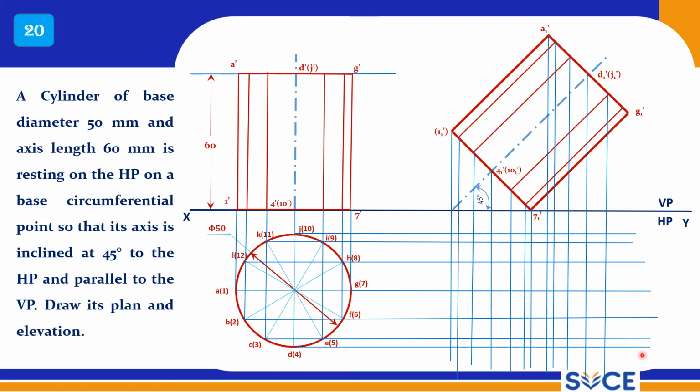Now you have to draw the arc from C10 to 4, and then 4 to D1 is a straight line. D1 to J1 should be an arc. From J1 to 10 it should be a thick line. These are the outermost lines.